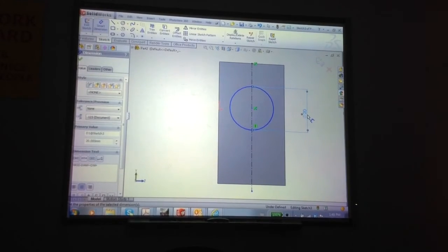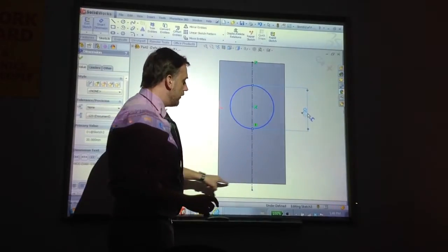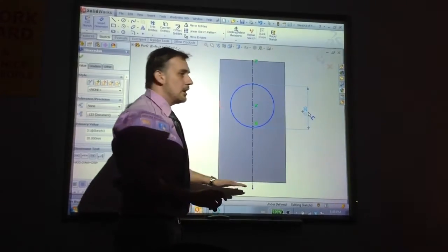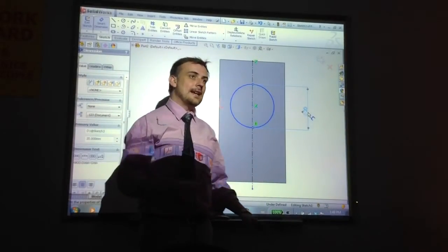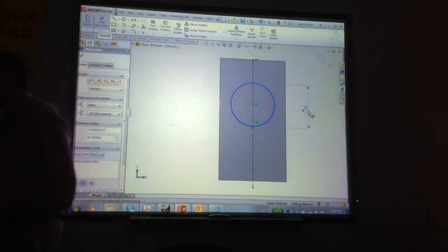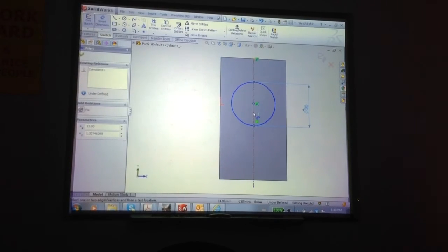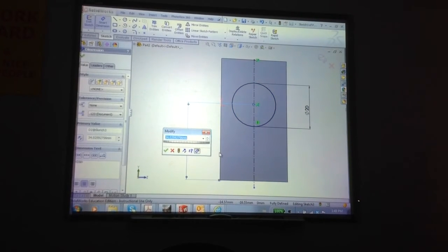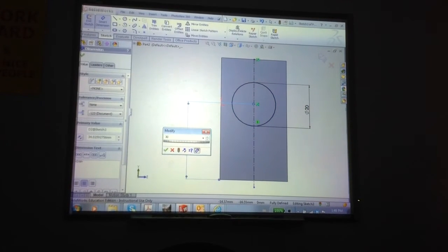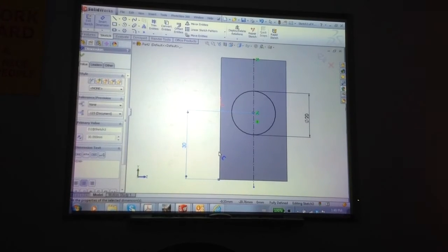And also I want that to be roughly 30 millimeters from the bottom of my dragster, so that when we have our starting gates, the pin is actually able to reach our canister. Okay, so just something to remember, it needs to be about 30 millimeters from the bottom. So click on the center of your circle and then the bottom edge, and that should be about 30, or no, it can be more than 30, but no less than 30 millimeters.